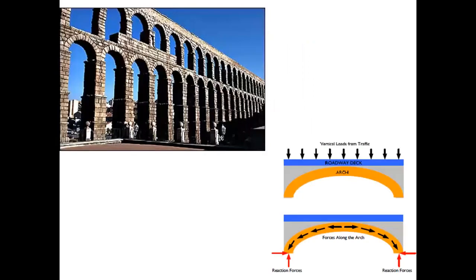Right. Now let's see how each bridge looks in the pictures. So this is an arch bridge. As I told you, an arch bridge will have only two ends, which are called abutments. This is how the arch loading acts. Whenever load acts on the bridge, this is a UDL load. This UDL load will transfer to the abutments like this. So this is how the load will transfer to the abutments, and horizontal and vertical reactions will be there at the abutments.